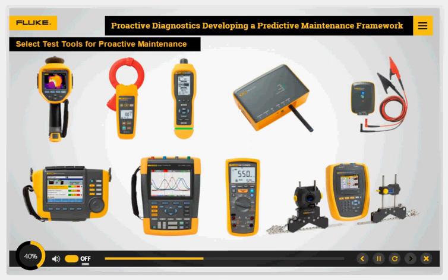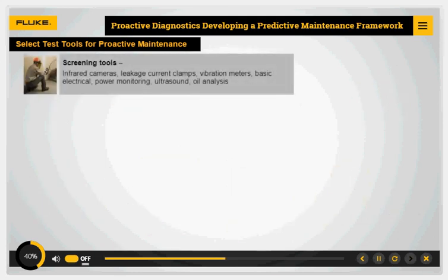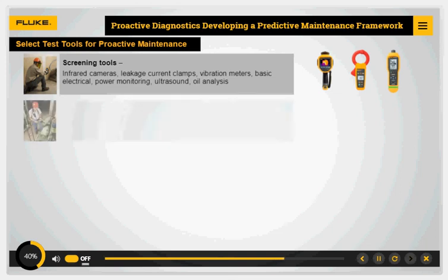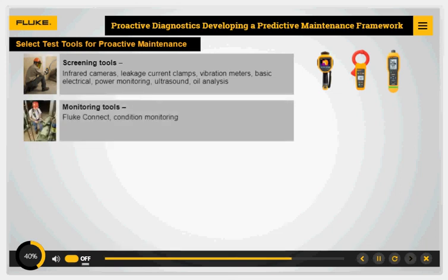Teams use different levels of tools depending on the type of inspection, system, and fault. Screening tools are used for the most frequent inspections to take quick go/no-go measurements for comparison and trending. These tools are often used together to simply spot an apparent change or difference, often saving the results for comparison during the next inspection. Monitoring tools are used when an asset is exhibiting signs of failure and a closer eye is needed on the system.